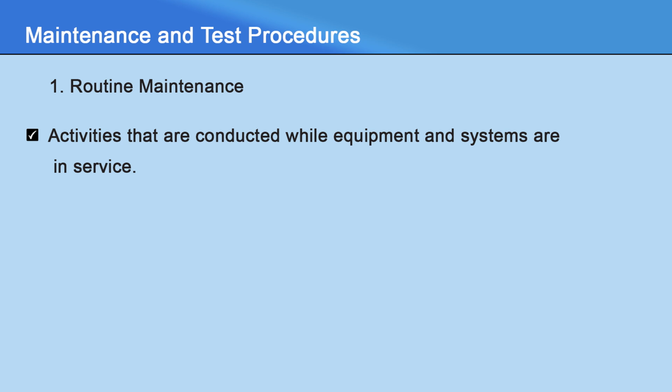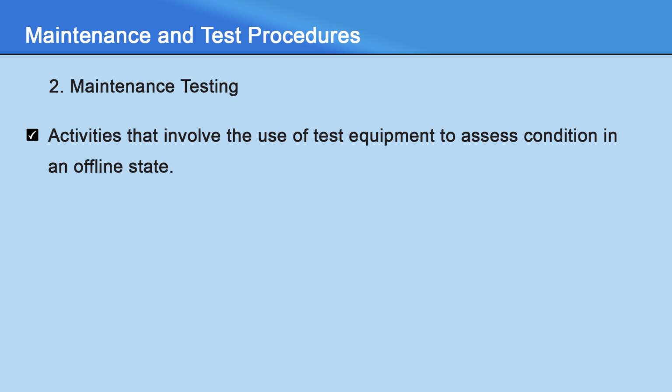Activities that are conducted while equipment and systems are in service are called routine maintenance. These activities are predictable and can be scheduled, staffed and budgeted. Generally, these are activities scheduled on a time-based, run-time meter-based or number of operations schedule. Some examples are visual inspections, infrared scans, cleaning, functional tests, measurement of operating quantities, lubrication, oil tests, governor and excitation system alignments.